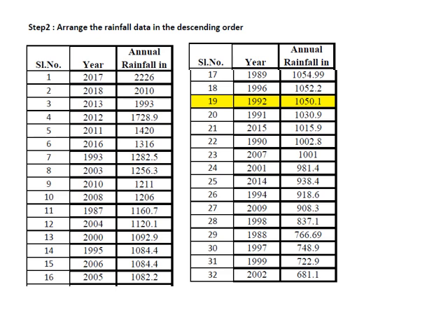It is not that whatever level you do the survey to, suppose you do the survey to 128 level, you fix the bund to 128. It is not like that. It is the amount of rainfall occurring in that particular catchment and how much of it is converted into runoff that is to be decided, and then the storage volume has to be decided.